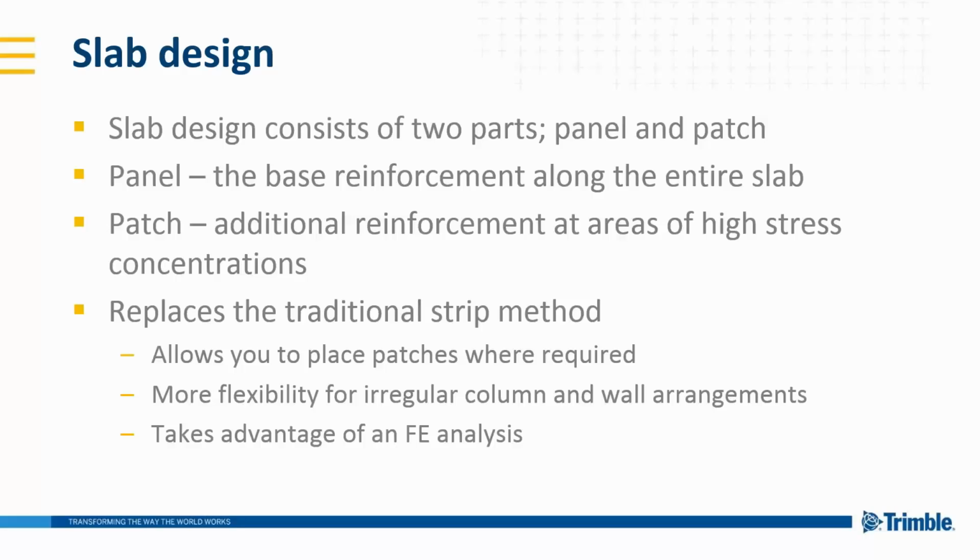In Tekla Structural Designer, slab design consists of two parts, that is, the design of the slab panel and the design of the patches. The panel considers the entire slab area. It takes the reinforcement required for the maximum moment and applies that to the entire slab. This is considered a base reinforcement and will be placed everywhere. The areas of high moments are then designed separately by the patches. In the panel design, areas within a patch are ignored, so the max moments are not used to design the panel reinforcement.